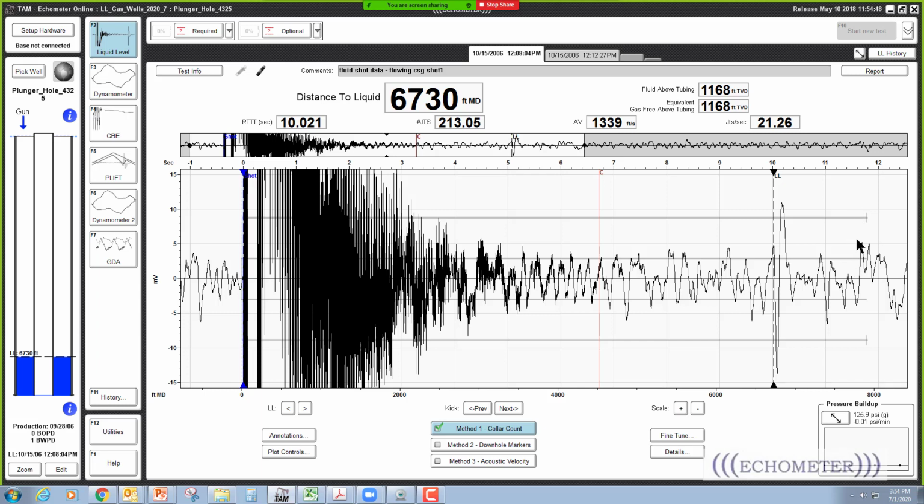And so every time you come to the gas well, if there's no packer and the casing valve's closed, the liquid level is going to be right there, always. And when it's not, you got to figure out why. And that's an important step in troubleshooting a gas well, because this fluid level can't be up here. It can't be up there because the gas can't flow into here and make it come up. The gas is going to come into here and push it out.